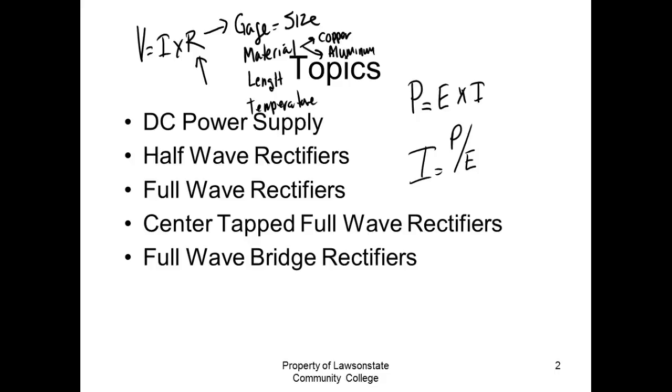The bigger the wire gauge, the more it's going to cost. If I go from copper to aluminum, aluminum has more resistance. Copper is very expensive. Aluminum, relative to cost, is quite a bit cheaper. Did you say copper has more resistance? I didn't. If I said that, I didn't. Aluminum has more resistance. I didn't think you meant to, but I'm like, maybe I heard it.